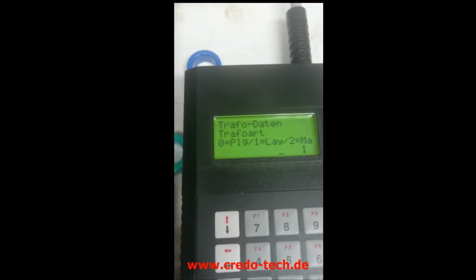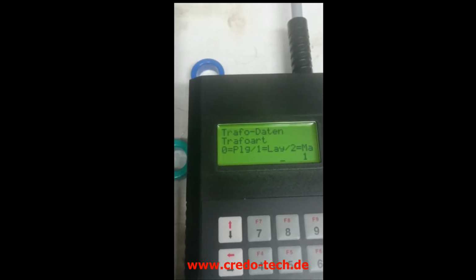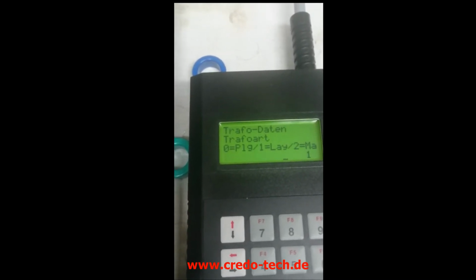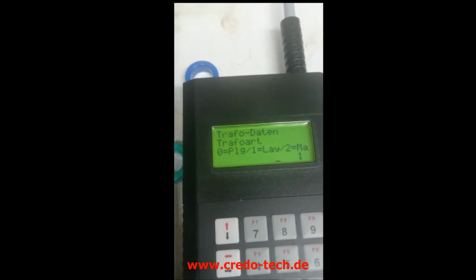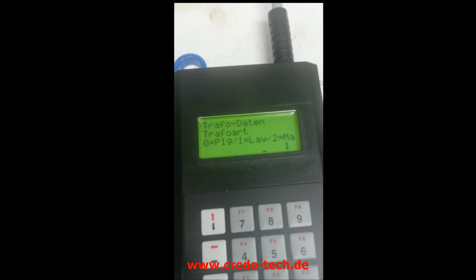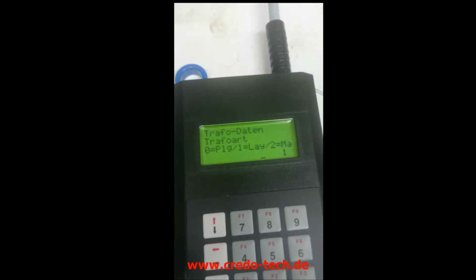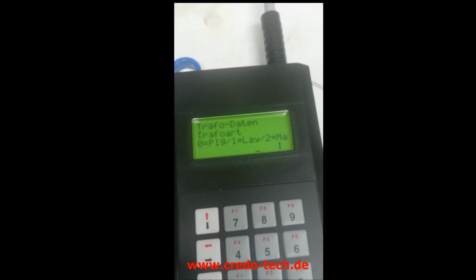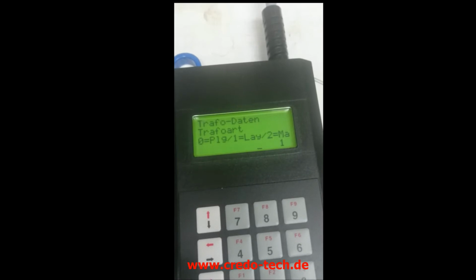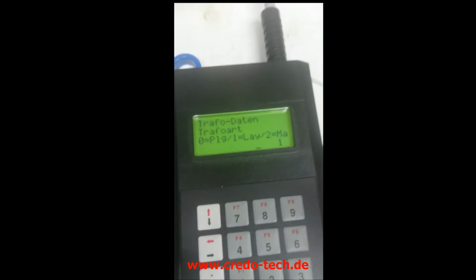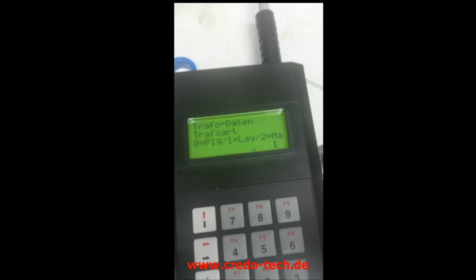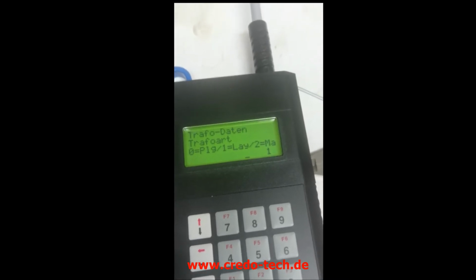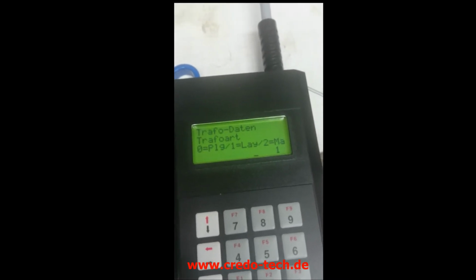We can set up the pitch to change each layer, because the outer diameter of the coil is getting bigger, so we need a different pitch as well, a different number of turns. Usually we reduce the number of turns by 6 turns each layer, and we have an additional factor for the co-rotation. I will show.